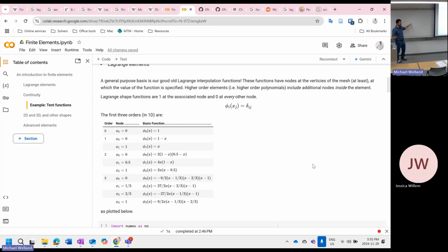This is the magic. This is the differentiator between finite difference and finite element. In finite element, your functions are still defined between your points. They're interpolated between those points and they're used that way. Finite difference doesn't actually look at that. It just looks at the values of it. So finite difference, I think, can actually be back calculated out of finite element for certain types of elements. This is a more general case.